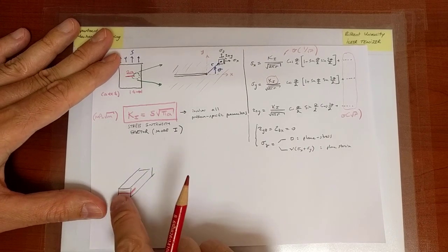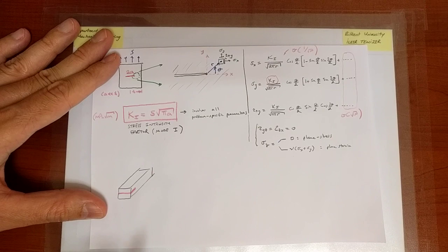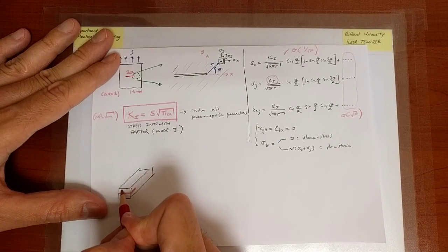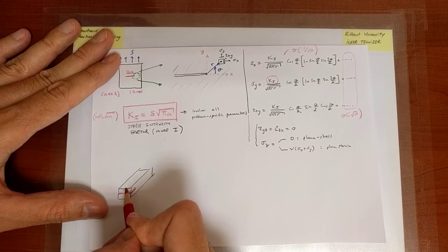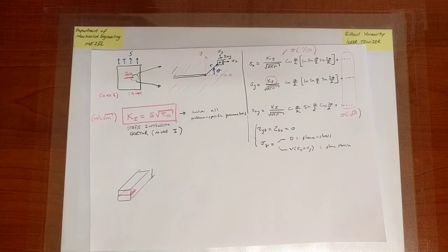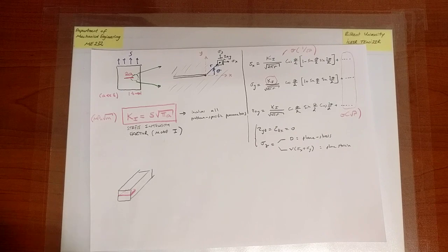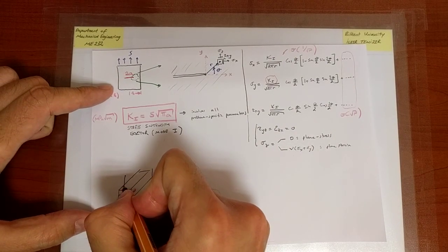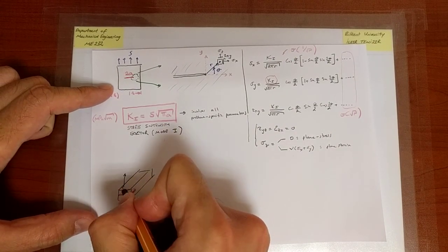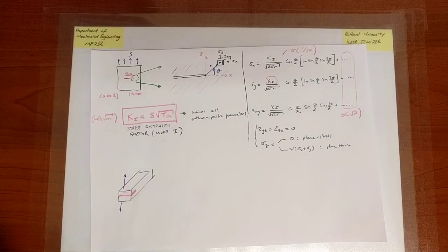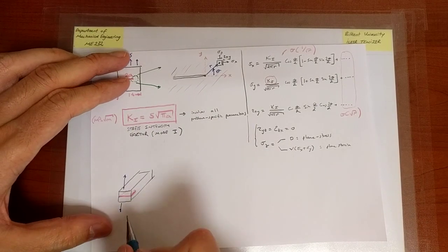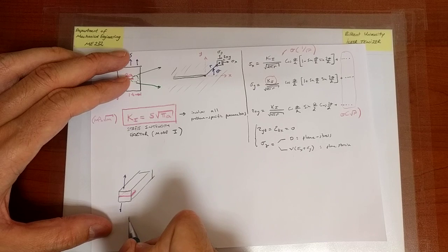I take a knife and just put a slit into this bar at this edge, okay, so that I create a crack surface. And subsequently what I will do is I will try to open that crack by applying a load at the top and bottom portions. So as a result, what I will obtain is a picture that probably looks like this.